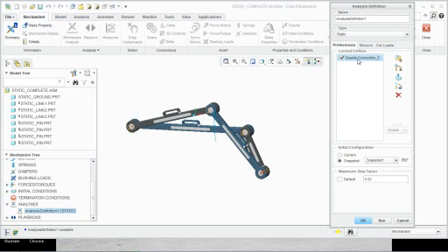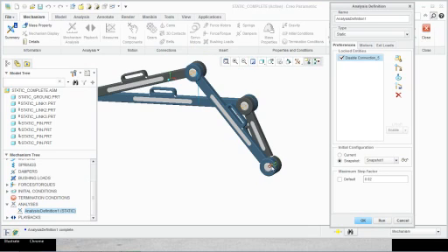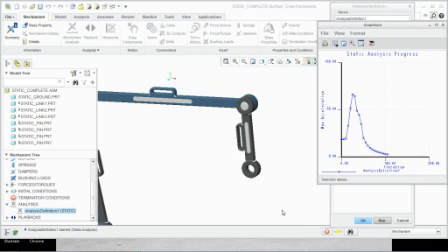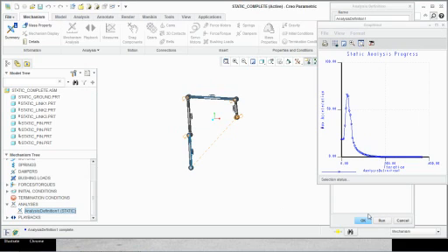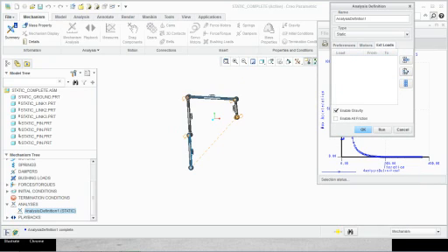Now if you disable the connection and you run again, now what is this connection? You can see it highlighted right here. So what I'm trying to say is, you know what, this is no longer connected. What happens? So let's say it starts from there, and you can see when the connection is disabled, I'm going to rerun this. So you can see that's disabled, so it comes down. Alright, so that's there. Now let's also go ahead and add our force torque load and rerun the analysis.